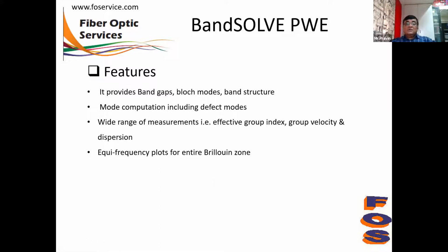So the band solve provides the band gap, Bloch mode, and the band structure. Mode computation includes the defect mode. It can give the effective group index, group velocity, and the dispersion. And also it can plot the entire Brillouin zone.